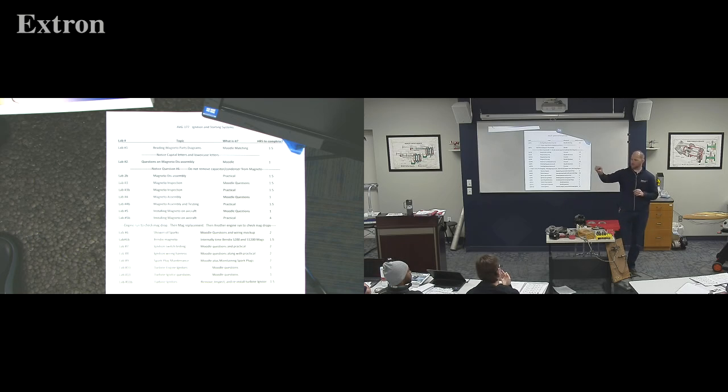Right down to this little bushing-looking guy that has a 1 on it, and I'm holding that up to show you because, man, it's hard to find these at the end of class. Try not to leave this at your desk or put it in the washer file. This is a very specific tool for testing our impulse coupling pawls, and we'll teach you how to do that later, but it's a very specific tool with specific dimensions. So we'll go over how to use that kit, but if you need to borrow it for driving stuff in and out, you could bring it to your bench, but we don't want you to.